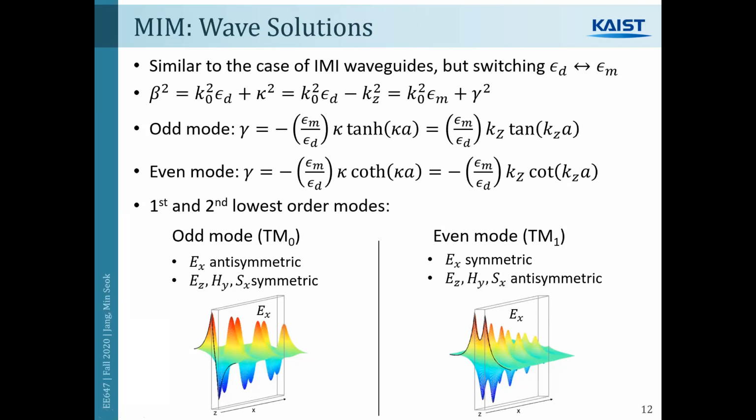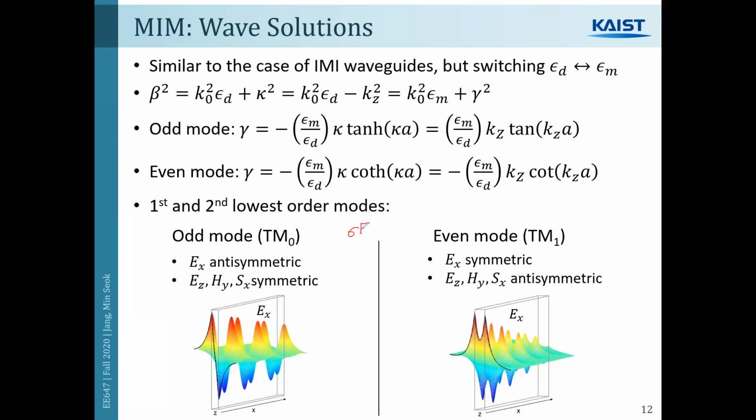By the way, Jihan asks, could you explain why a metallic waveguide has high loss? Well, that is really related to how you create heat inside the material. Let's say you have a conductivity here. Conductivity times E gives you the current density, right? And then the power dissipation is determined by J dot E, right?